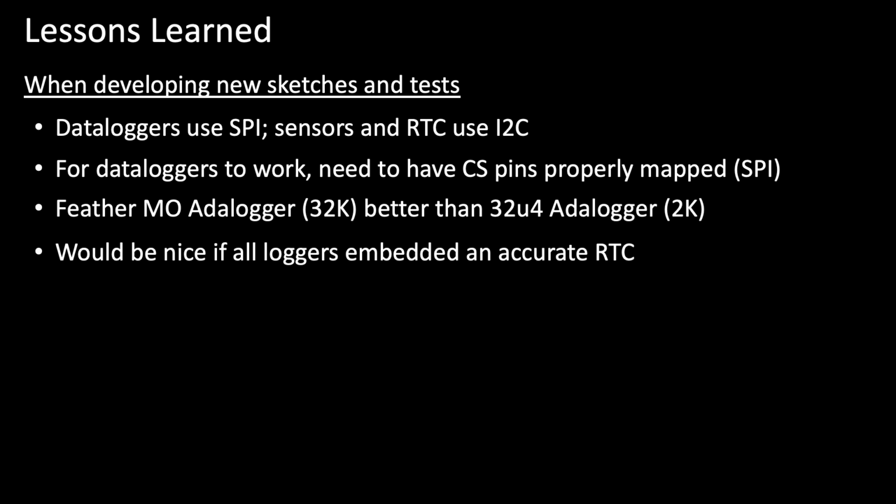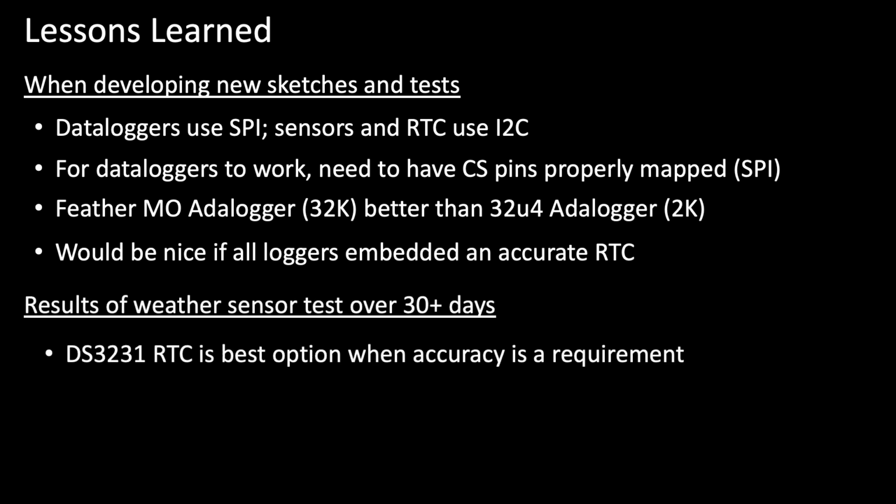And in my opinion, it would be really nice if all the loggers embedded an accurate real-time clock. The Adalogger boards actually have the PCF8523 by default. And we already talked a little bit about some of the accuracy issues with those particular real-time clocks that need to be considered in code. It can be fixed, but it just takes a little bit more work. I would just like to have everything embedded in one package: a data logger with a good RTC functioning on a microcontroller that has plenty of memory.